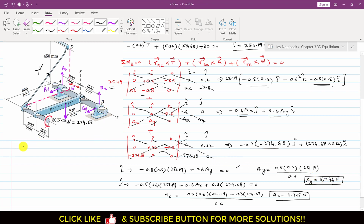Now to find the reactions BX and BY, we can apply the summation of forces along X equals to 0, right? So we can write that the BX is acting in the positive X direction, so I will write BX, then we will write AX, so AX is 11.745, and then in the X direction we have this W force which is acting in the negative X, so I will write minus 274.68, and then this T has one component in the I direction, right?